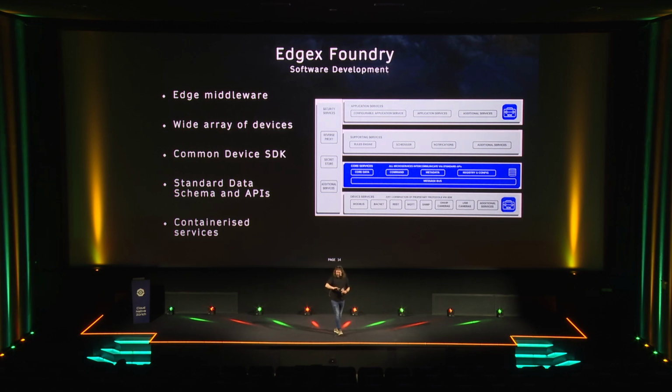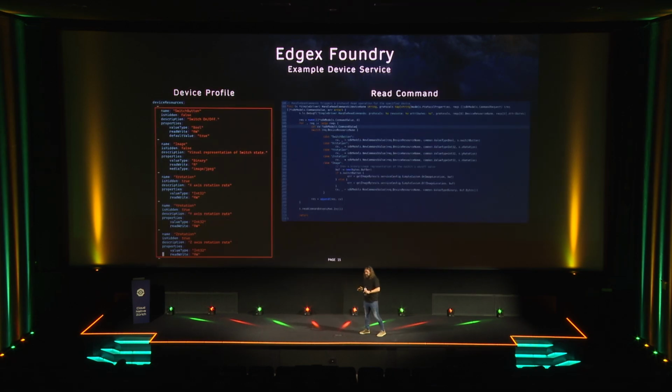But the device service is what I'm going to focus on here. There's so much to this, but essentially there's a pre-existing set of device services for all sorts of standardized hardware. So things like USB cameras and Modbus, which you would see in manufacturing a lot. But even REST or MQTT, if you want to think about interacting with an external system as a data source or a device. But if you have a custom piece of hardware that you need to develop a device service for to bring it on board to EdgeX, they make it quite easy with their SDKs. They have SDKs in Go and C, and I think Python as well.